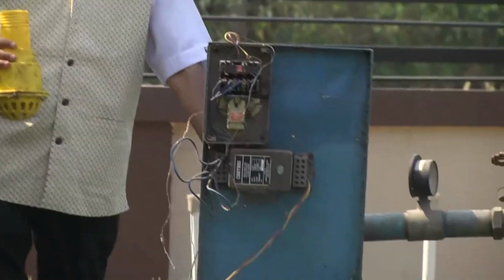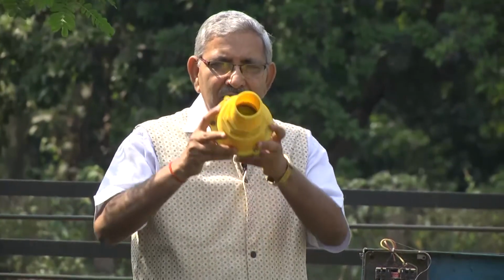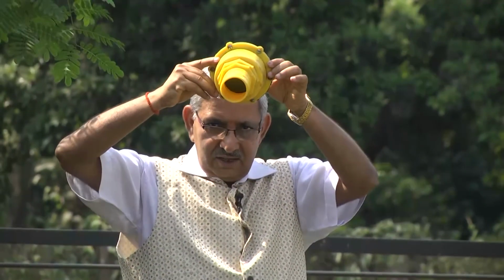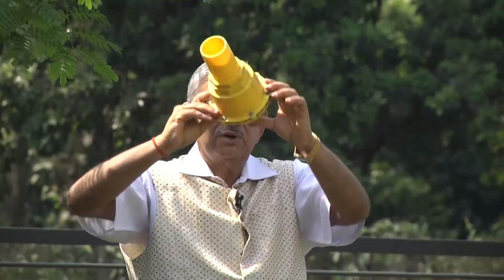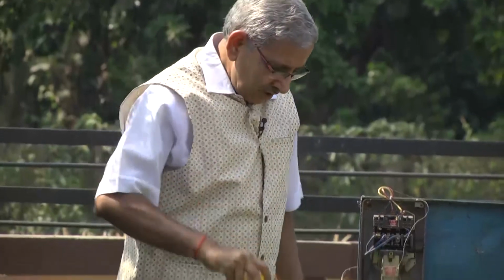First, the suction pipeline is filled up with water up to the impeller, so that it does not take air. Whatever air is available in the pipeline will be removed when it is filled up with water, and this is used for priming. You can see here at this end there is a flap, and when we are filling water, this particular valve gets closed. That is the purpose of the foot valve.